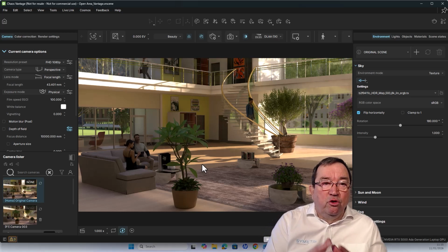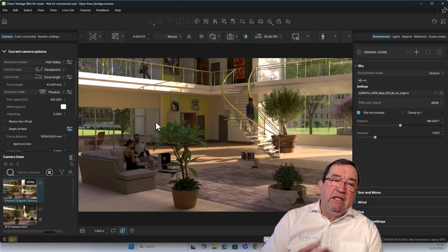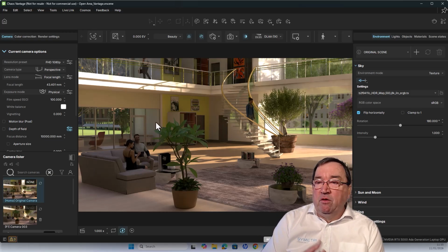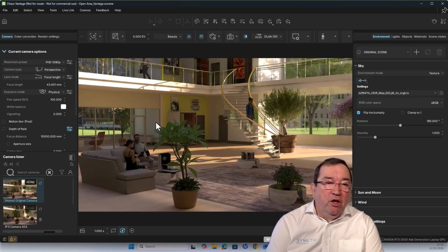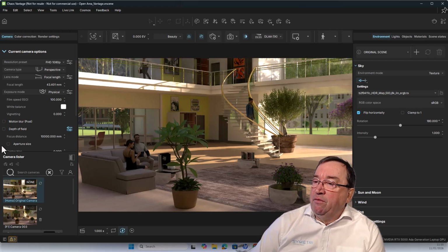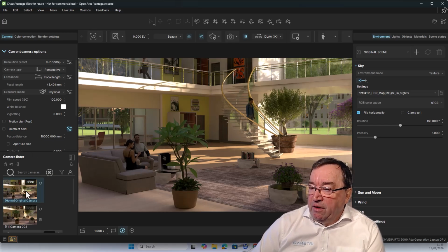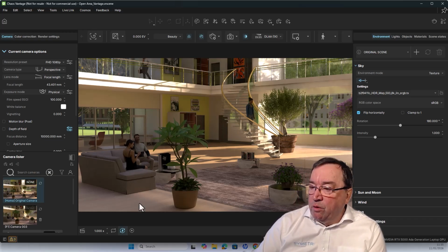I don't want to go deep into the intricacies of Vantage because it's absolutely great. But one of the areas I do like is that this view, when I'm rendering in V-Ray, in Max or Corona, when we have things like focal length, or blur or any blurs, it takes a long time to render. So in my view here, I've got field of view, this type of thing in here. So if I click on some of the other camera views I've made, like this view down here, you can see that I've got a slight focal length in here.